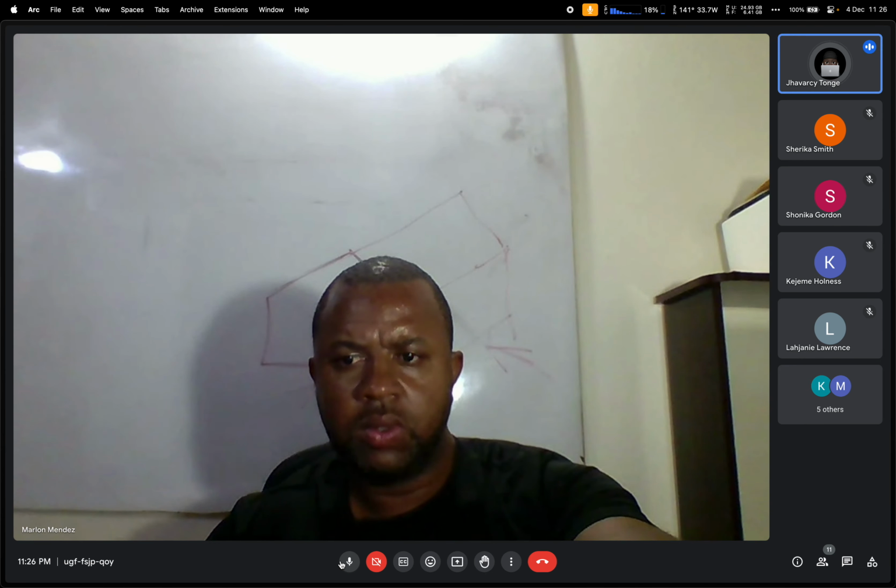So these are the conditions to be met. Three or more spans in each direction. There is a criterion that adjacent spans should not vary by more than a certain percentage. The live load should not be greater than twice the dead load.